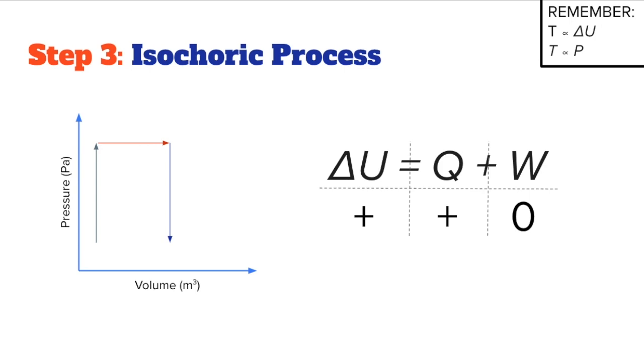The third process that the can endures is isochoric. However, this time the pressure of the can decreases. This will create a vertical line on the P versus V graph. During this stage, the steam within the can pushes the water out of the straws to thrust the boat forwards, which results in a decrease in pressure within the can without any change in the shape of the can.